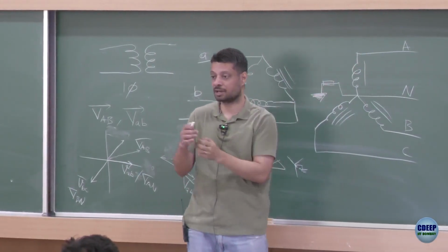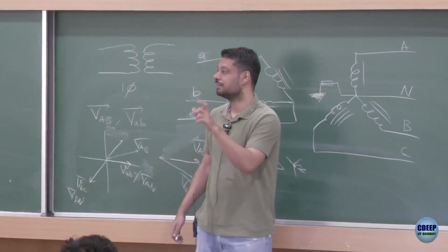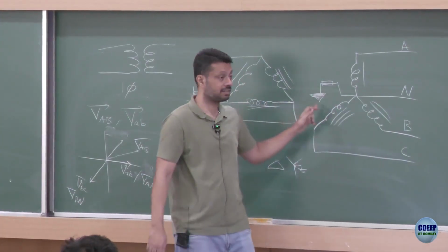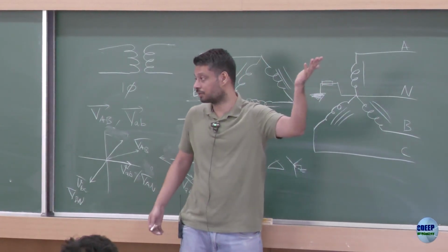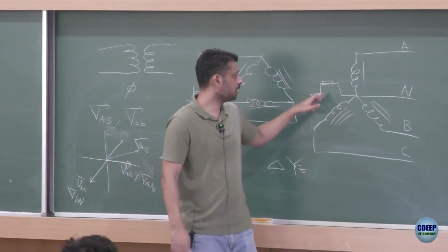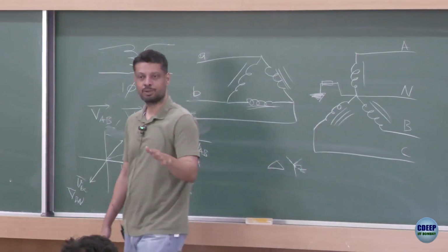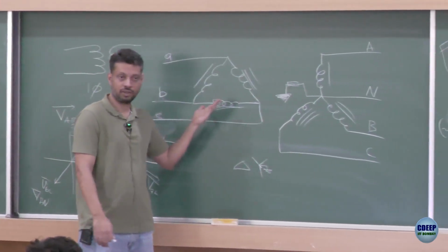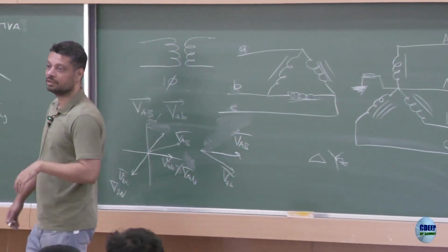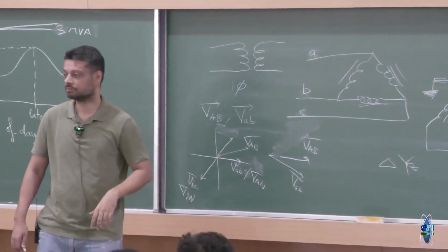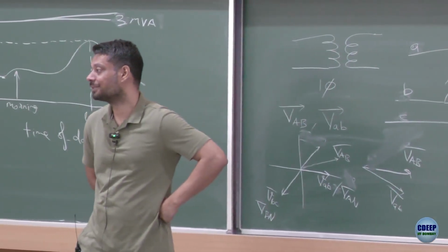So, you can design your gloves, you can design your shoes, you can design the insulators on that well defined 400 volt. If this is not earthed, I am standing there, I touch a line, I don't know how much voltage will get applied across me, right. So therefore, load side it makes sense to have a star, right. Then the question is on the source side, on this side, you could have still had a star, right. Why do you want a delta? That's the next question now. Difficult question. Anyone who has answer?